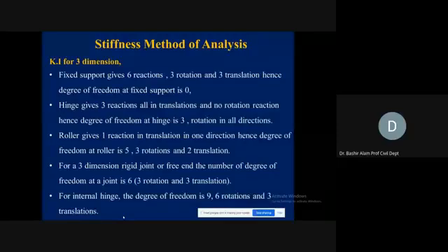Okay, so kinematic indeterminacy for 3-dimensional. Fixed support gives 6 reactions, and 6 reactions means 3 moments and 3 translations. 3 will be in 3 dimensions. So hence degree of freedom at fixed support is 0.